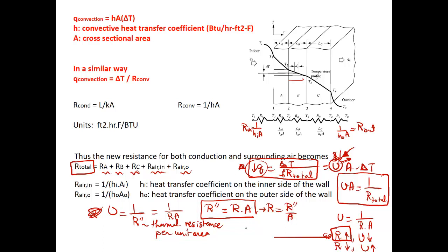Now there's a big misconception or a big mistake that students make. When you add the thermal resistances, don't add U. So if you have the U value tabulated, don't use the U to add here. No, we always add the resistances, because those two, as you see, are inversely proportional, U and R. If you change the thickness, don't just simply change U. You can't directly change U with thickness.